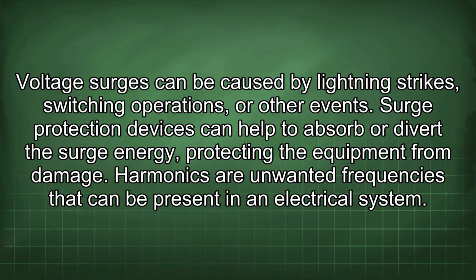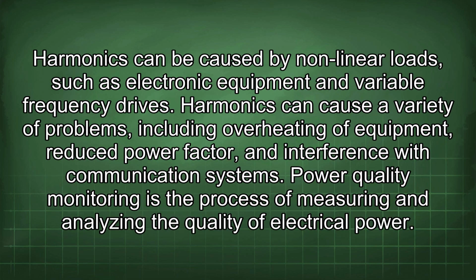Harmonics are unwanted frequencies that can be present in an electrical system. Harmonics can be caused by nonlinear loads, such as electronic equipment and variable frequency drives. Harmonics can cause a variety of problems, including overheating of equipment, reduced power factor, and interference with communication systems.